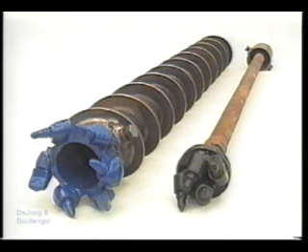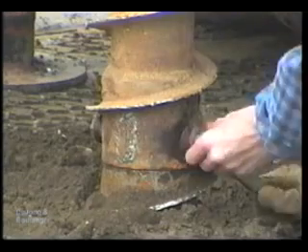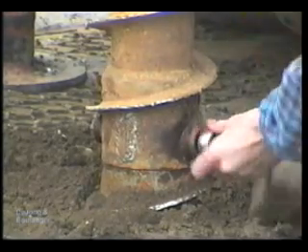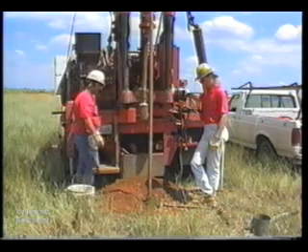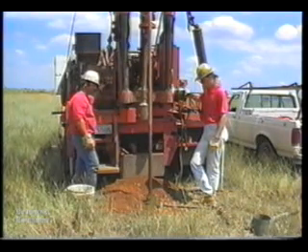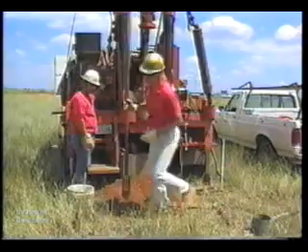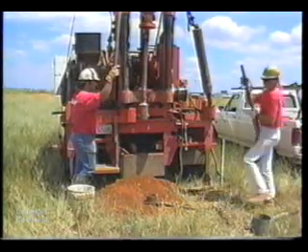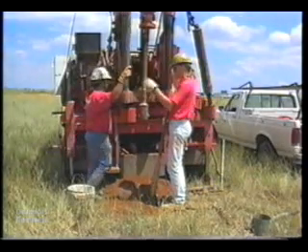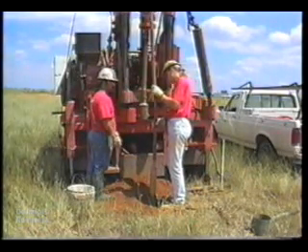The basic hollow stem setup is shown here. The inner bit is connected to drill rods that run through the hollow stem, and the other bit is bolted to the bottom of the lead auger. While drilling, the inner and outer bits rotate together, cutting and loosening the soil at the bottom of the hole. The soil cuttings are carried upwards by the auger flights to the top of the hole. To sample, the drill rod to cap adapter is removed, and the drill rods and center bit are withdrawn from the hole. A sampler is then connected to the bottom of the drill rods and lowered down the hole for sampling. After sampling, the center bit is reconnected to the drill rods, lowered back down the hole, and drilling is resumed.